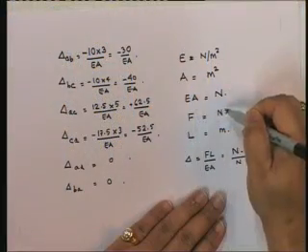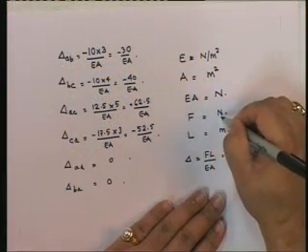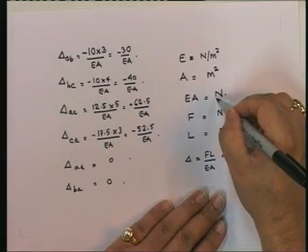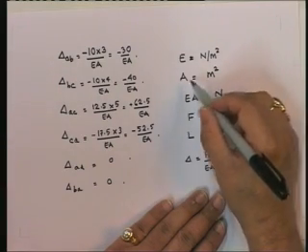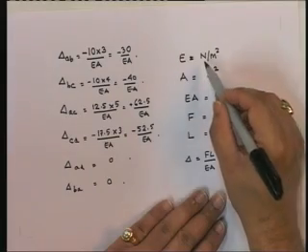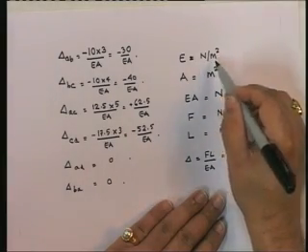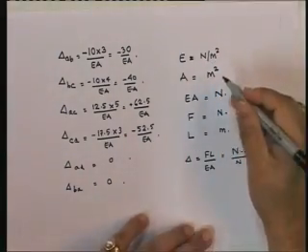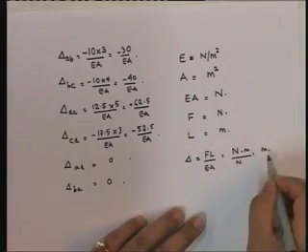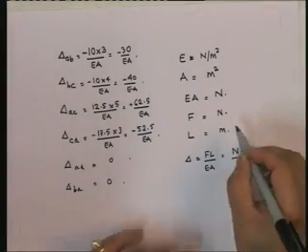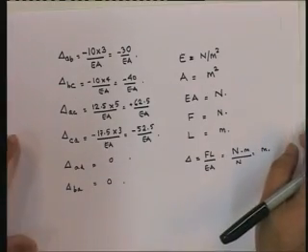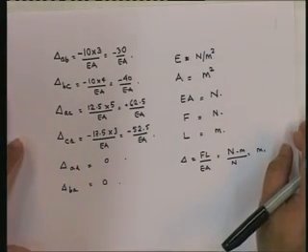Here I'm not doing that, however I am just trying to state here that you need to bring everything down. If you want to make F in kilonewtons, then EA also should be in kilonewtons. If you make this area into millimeter squared, then E also needs to be in Newton per millimeter squared. Consistent units will always ensure, and then your delta will be in millimeter, by the way. So as long as you are consistent, you shouldn't have a problem with units.